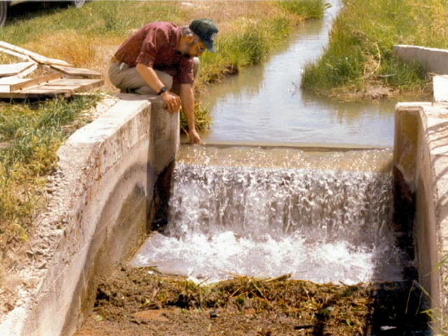For small farm ditches, the height of the drop in meters should not exceed 0.3 times the land slope in percentage. A drop of more than 1 meter, that is about 3 feet, high should seldom be used. With large streams, this height is sometimes increased. On steep slopes, it is often advisable to use a concrete lined ditch section or pipeline to lower the water.